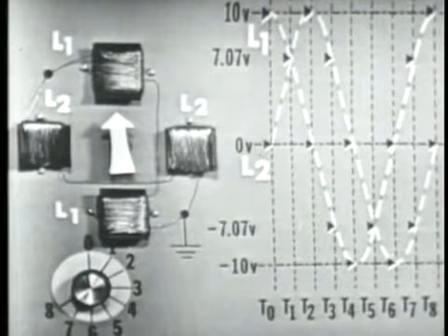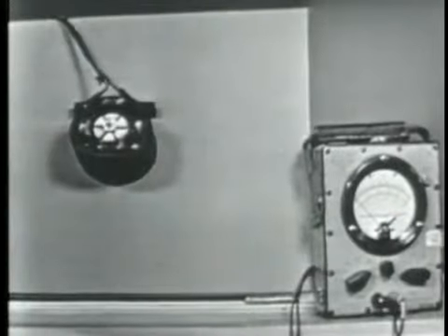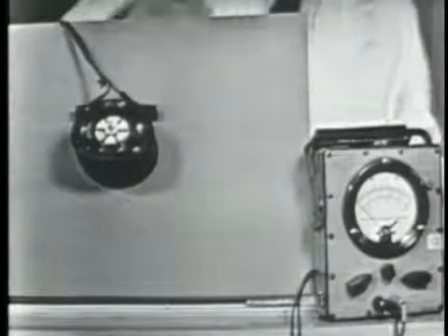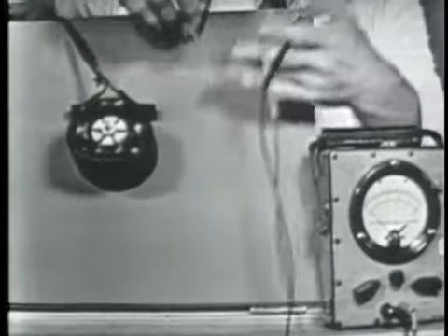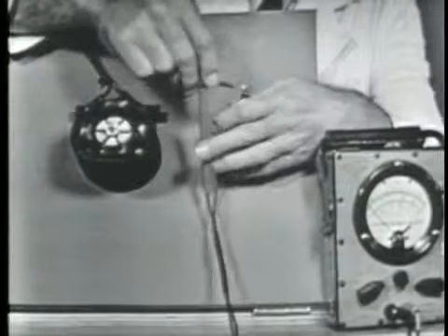Right. Now, I'll take item 4. All right. Help us out. All right, item 4, the rotor acts like a magnet. Well, it actually becomes an electromagnet, right, and follows the rotating magnetic field because of induction.